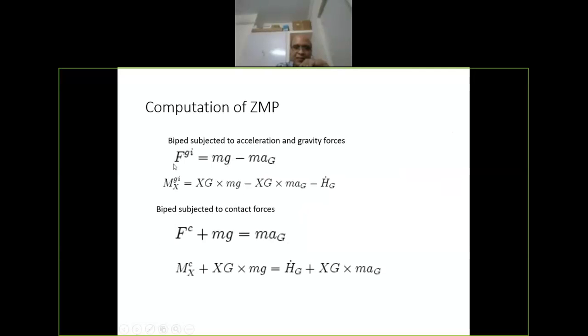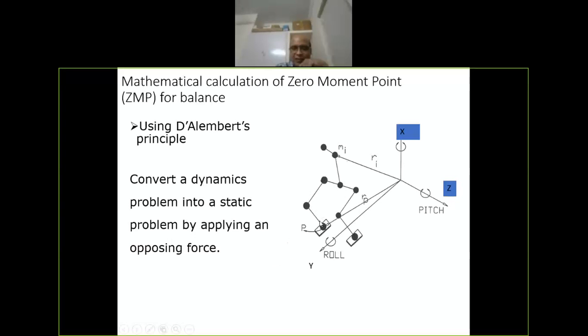So that's the top equation. So the total force is equal to mg minus ma, which is the total force which is acting on the leg on the ground. Now, the force which is acting on the leg on the ground will be pointing downward, okay, because it is supporting the weight.